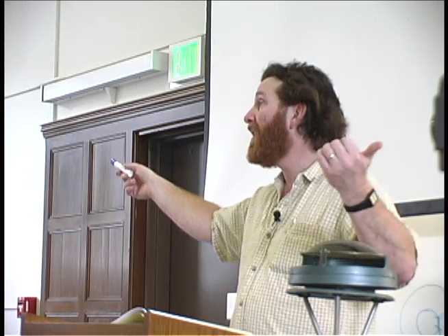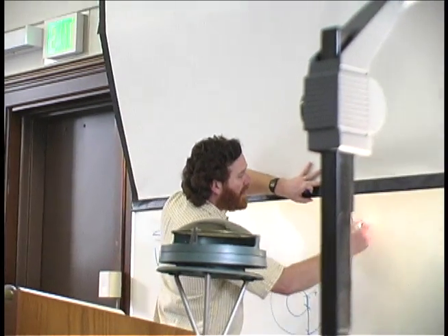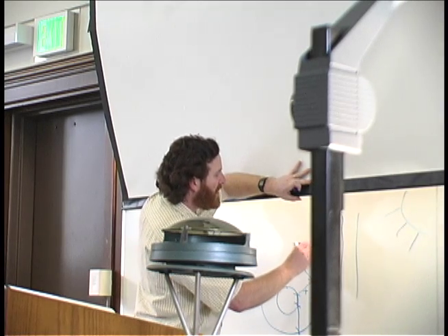One of the biggest challenges to passive solar around here is most of the views are east and west. And, you know, people want to be looking at the views. So they've got all this west-facing glass, and then they've got reflection off the lake, which can add to another 35%. So what I do on west-facing windows, it's called low E squared. So normal low E glass has, okay, here's the sun out here. Here's you, stick figure.